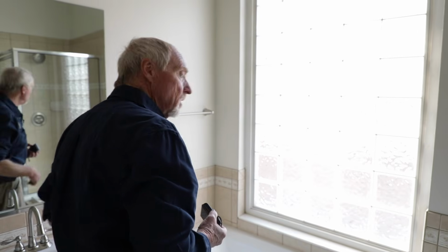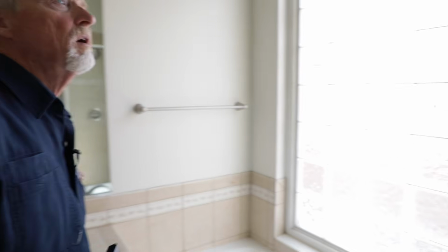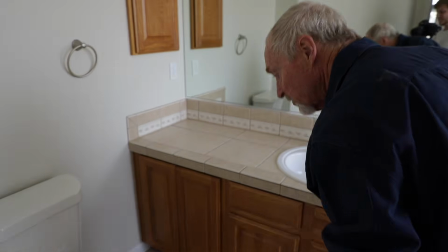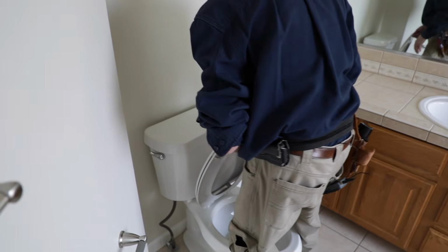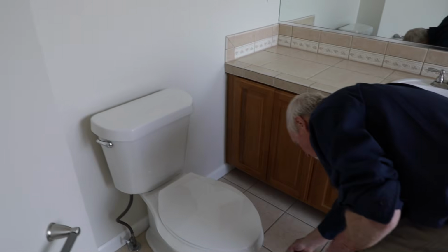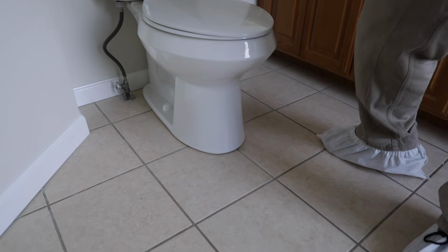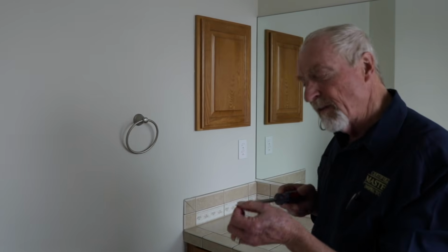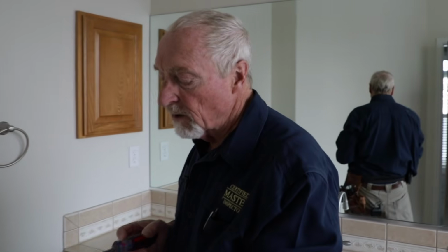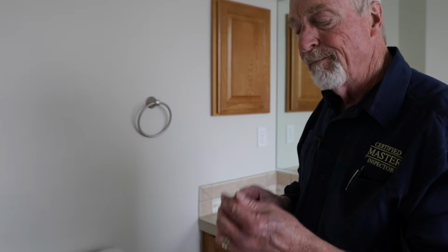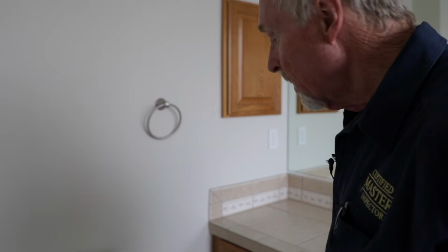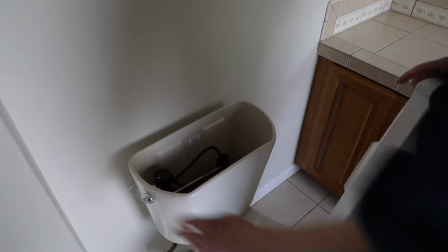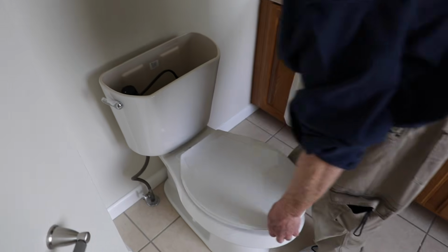I'm looking at my window here, which looks pretty good. And now back into the regular routine here. Check the toilet. I'm going to check and see if it's nice and tight. It is. Take my big screwdriver, check the bottom, see if I have any caulking hiding under there. I'd get a dull kind of feel, and I'd feel it squish against the caulking if it was caulked underneath. I don't get that. I'm thinking it's not sealed or caulked to the floor. I call it out. Take a quick look inside, of course. See how it flushes.